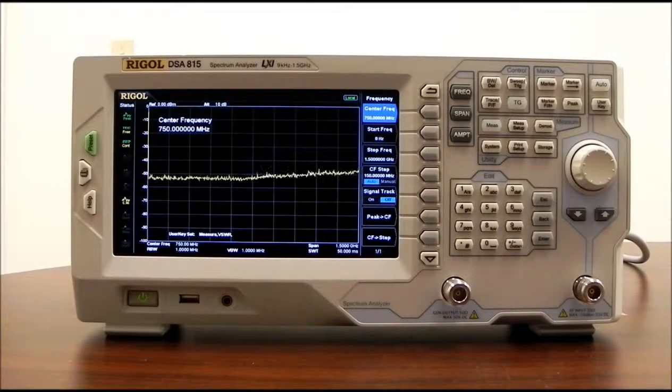Some typical applications are monitoring RF or radio communication channels. How much bandwidth a particular channel may be taking up is a pretty common example. Measuring filters if you're designing radios, or you're using filters to help to clean up some of your signal levels. You can then characterize the filter with respect to frequency using a spectrum analyzer and a tracking generator, which we'll get into a little bit later.